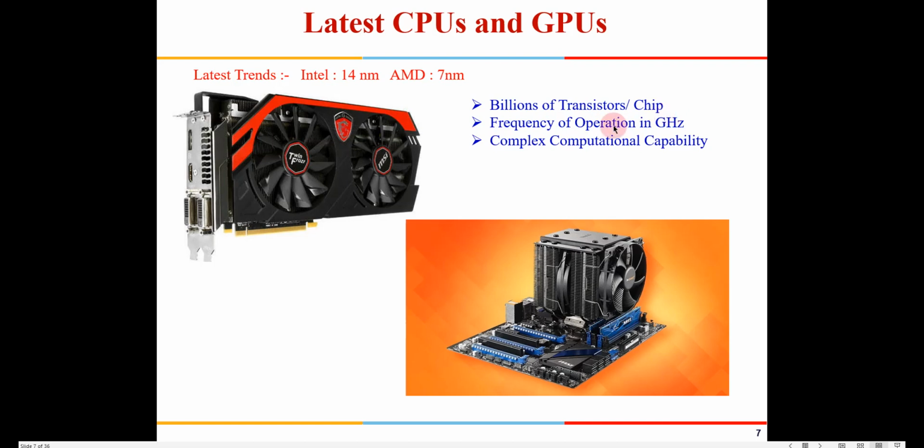If you have a single metal layer, routing becomes difficult. In the latest chips you have around 10 to 13 layers of metal, each separated by an insulating layer, and then you have wires which can interconnect these metals. So you see the routing has now become very compact.